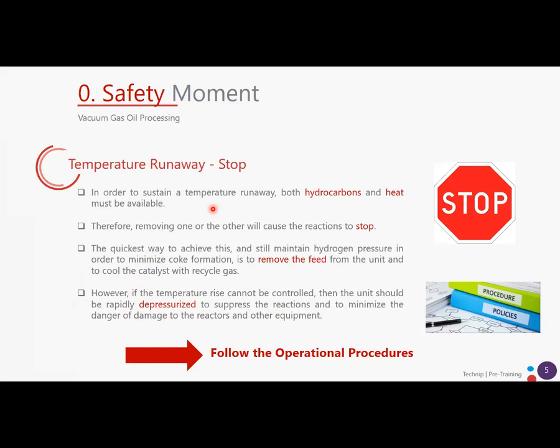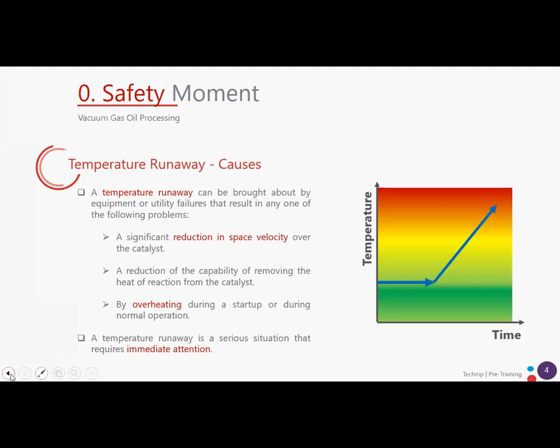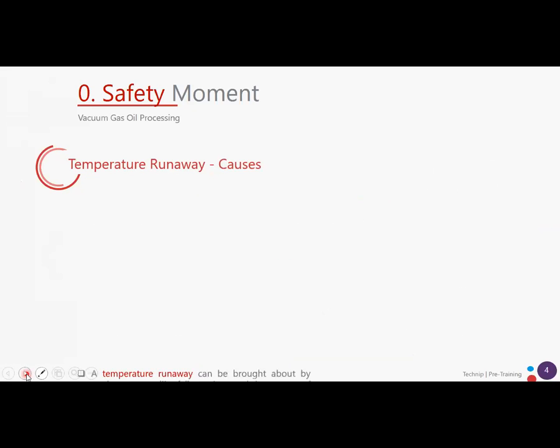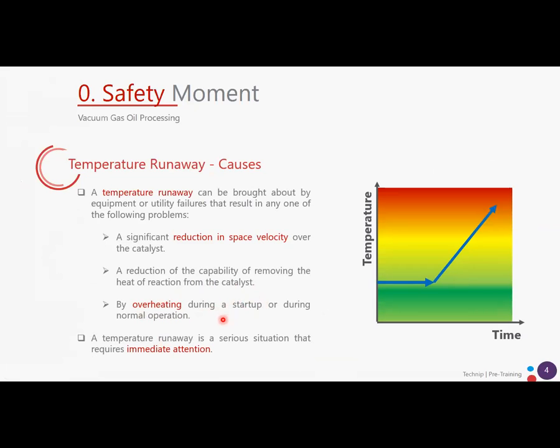Also, it is important to avoid very high temperature during the startup, and a proper catalyst loading is part of that. You have to be very careful when you load the catalyst to avoid any overheating in some places of the reactor. So this is a safety moment that we wanted to share with you.